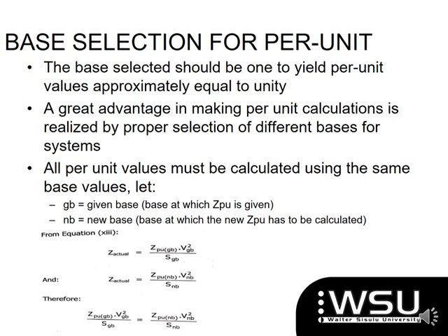But for me, I prefer to utilize the largest one so that I make sure that all of my other ones are below 1 and only there is one that is going to be sitting at the unity value. So to be on the safe side, if you're not given one, look at your network and then choose the base value that is the highest out of the components that you have.